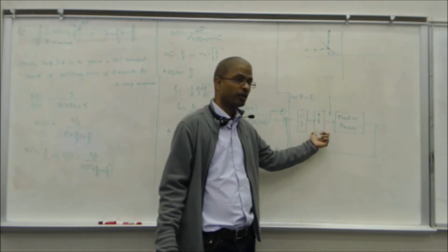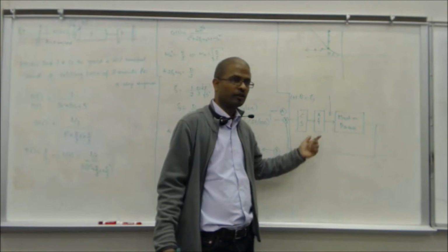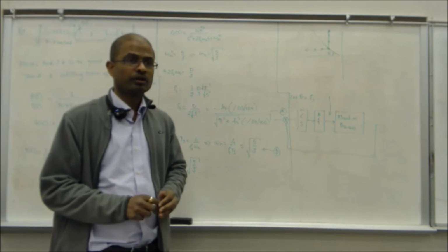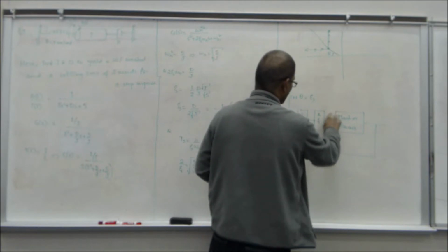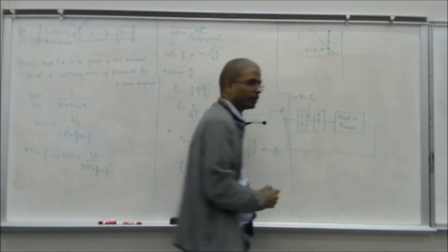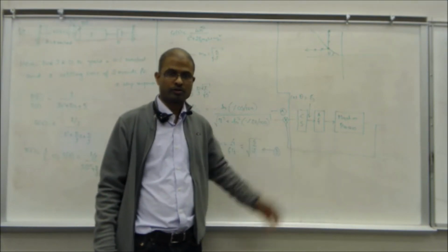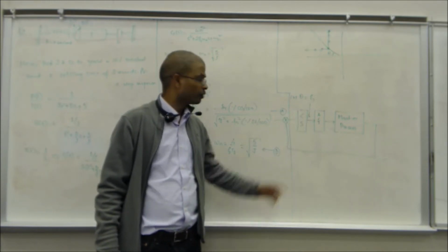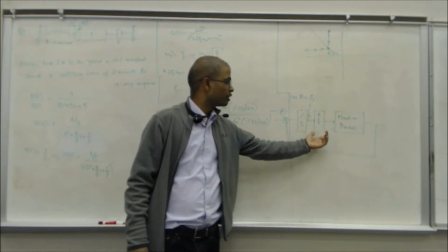Now, when you're actuating, you cannot assume the actuators are only going to get commanded by the control system. If there is high wind, the actuators are obviously going to get affected by that, right? So you should take that into consideration. That is like a signal coming in. Apart from whatever the control system is commanding, there's going to be some signal coming into the actuators. You have to be able to ignore that.